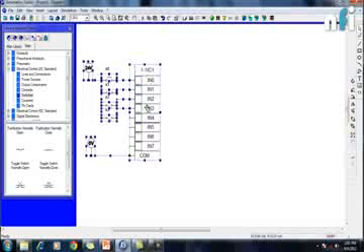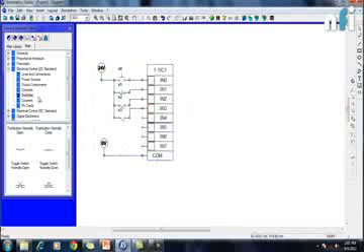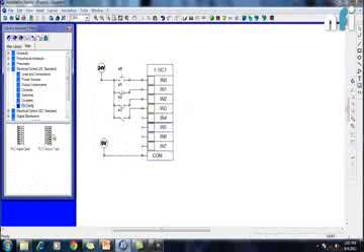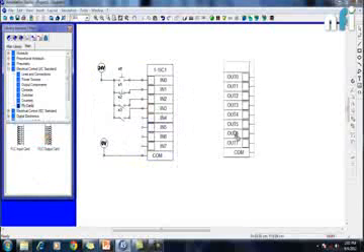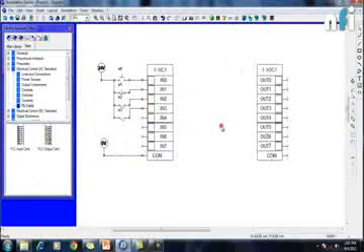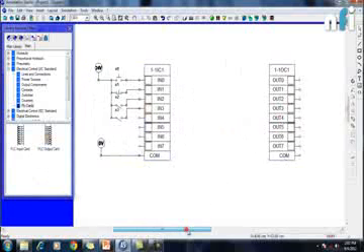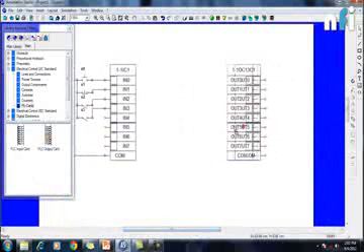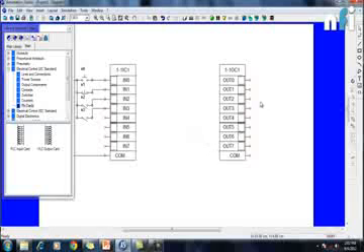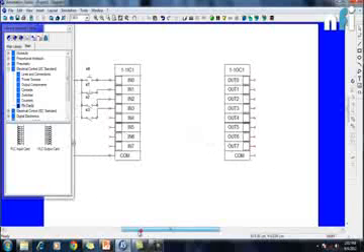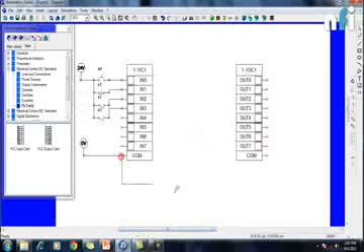Now let's see what happens at the output terminals. For that, I'm going to have this output card from here. You can see like this. Okay. So I'm placing this output card a little bit away from that to make the concept pretty easy. Similarly, we have different outputs, out 0, 1, 2, 3, 4 up to 7. Then we have a common output. Now similarly, I'm going to connect this 0 volt. I can take the wire from here to this common output.